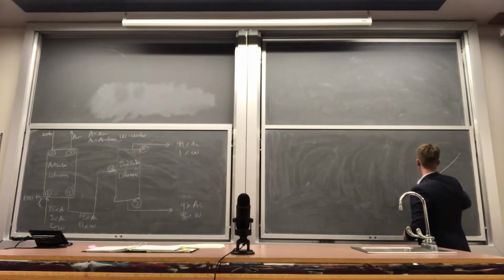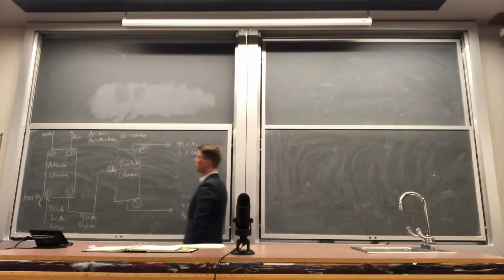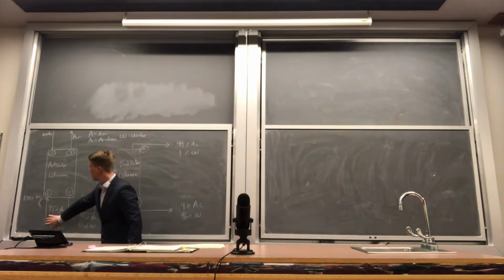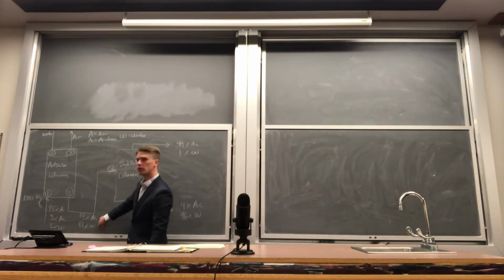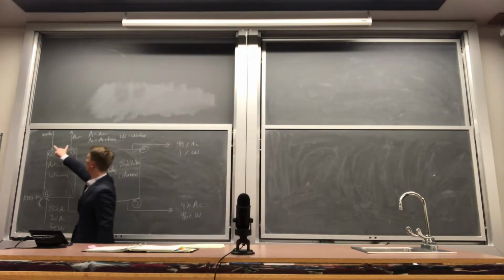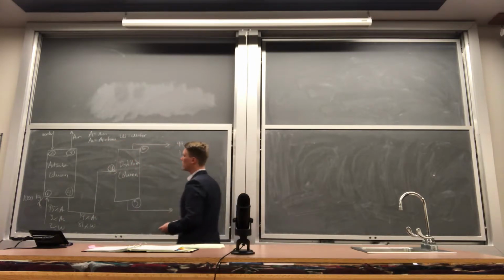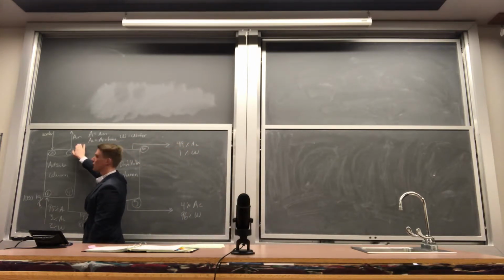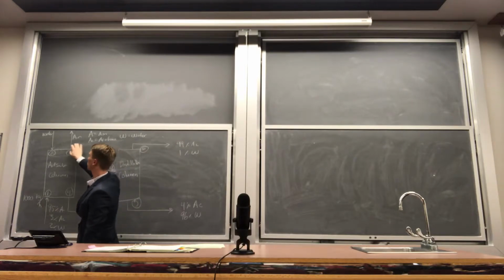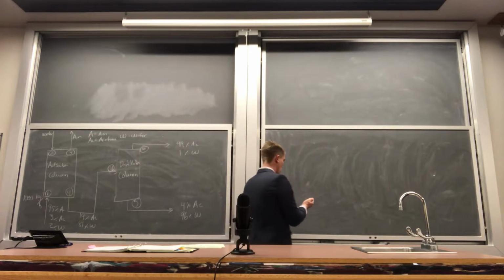Let's write out our unknowns. Fortunately in this problem, the composition of every stream has been defined: the feed to the process, the stream connecting it, and the 2 product streams coming out. And these 2 here are pure streams as well. In the future, we know it's going to be difficult to get pure air coming out of the top, so we'll have some impurities, some water evaporated. But for this example, we're oversimplifying and saying it's just pure coming out of the top and just pure water coming into the bottom. So our unknowns.